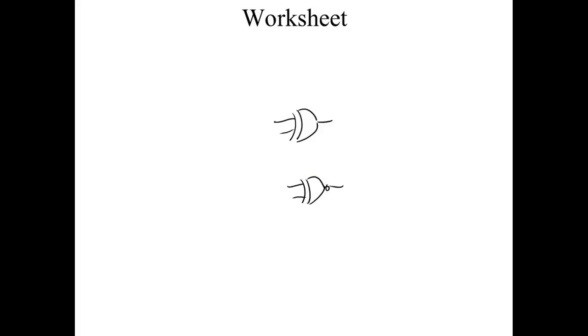What are we going to do? Nobody's got any idea. I'm going to come over here and do this. And now we've got an exclusive NOR. So the lab kit doesn't have both of these. They've got an exclusive OR, and then you just add that inverter, and you'll get the exclusive NOR function, but your output will be out here. Y'all understand?